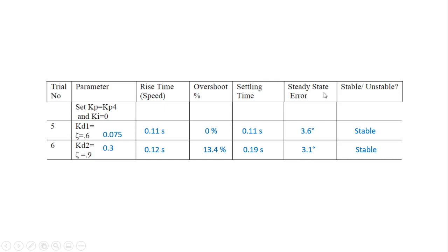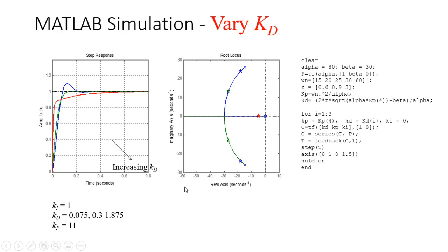So here it is. What did I do? I actually ran these cases and read those values. They're both stable, and the steady state error, is it about the same or did it decrease? And settling time looks like it increased. The system became underdamped, and rise time is about the same. To figure this out, I think the best way is to look at the root locus.